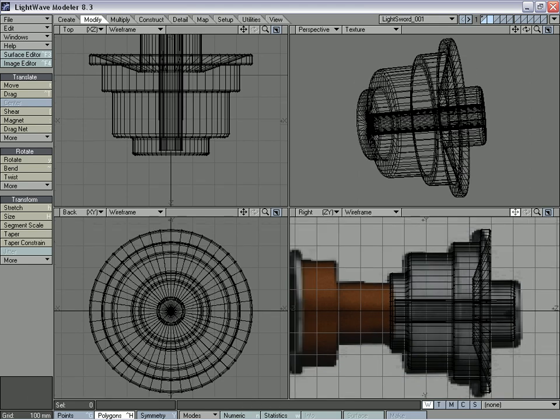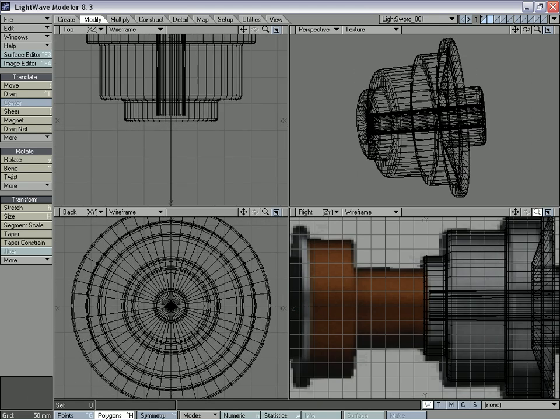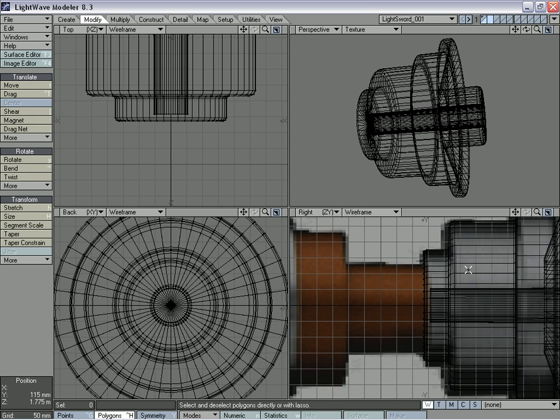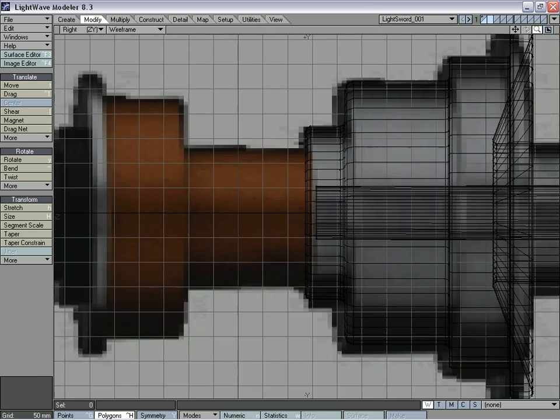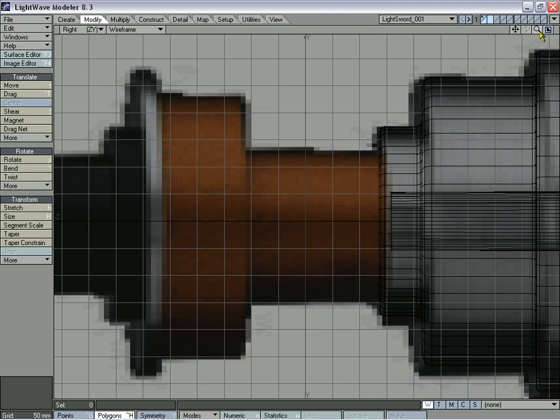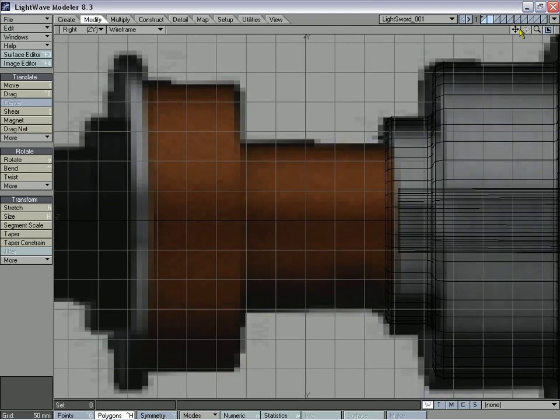Okay, we're going to model this next section the same way that we modeled the other one. Hit the 0 key on the numeric pad, the number pad, to maximize that viewport, and Shift plus for the points tool, and create a point right here. Going inward just a little bit, so we're going inside that other section, and then come up here and 3 points, kind of a tight curve on that, and 3 points, a little bigger, and then 1. And this is a fairly simple section.